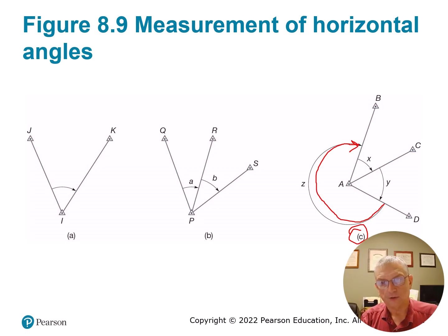But say, for example, the sum of angle X, Y, and Z comes to 360 degrees, 00 minutes, and 6 seconds, then you would adjust each of your observed angles by adding 2 seconds. And the closing of the horizon, the angle Z there, confirms that you don't have something blown any worse than 6 seconds in that little example.